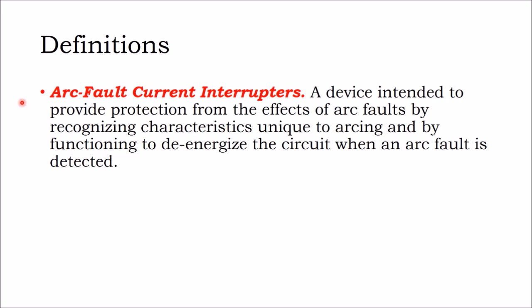Nowadays, most inverters will recognize arc faults, and it's interesting that previous iterations of inverters did not detect arc faults. Now when I turn on an array, I'm used to having my owners say, well, I never have any kind of maintenance issues, but I've already had one owner with an arc fault issue, and it's changed my whole line of thinking on solar array maintenance.